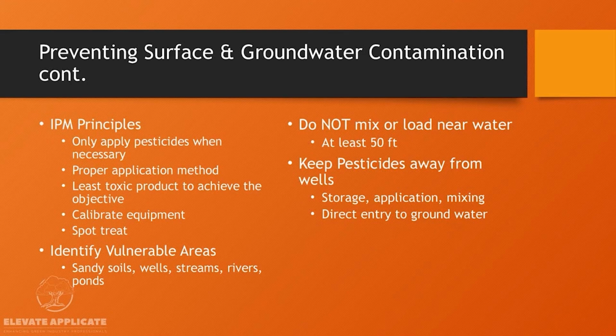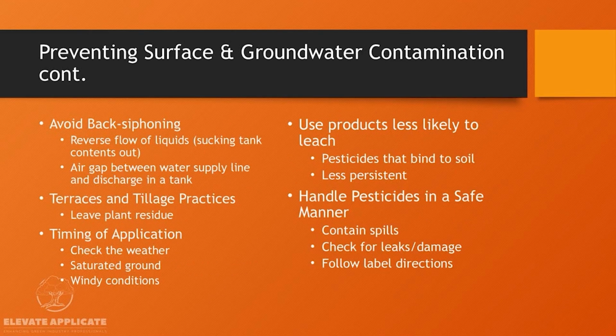Be conscious of that. Also, do not mix or load near water. Try and stay at least 50 feet away. That can't always happen, but you can do your best to do that. And then also keep pesticides away from wells. That goes for the storage of it, the application, mixing, because those wells are direct entry into the groundwater, and we don't want to contaminate that. Remember, it's really hard to decontaminate groundwater.